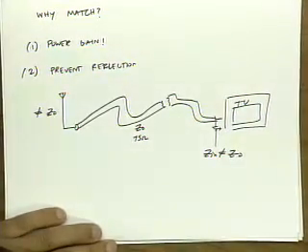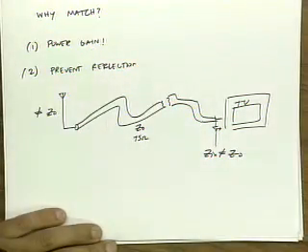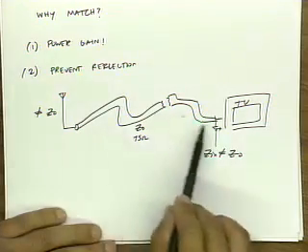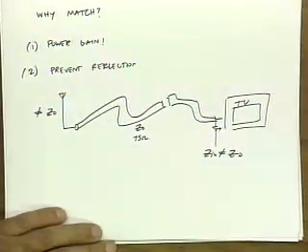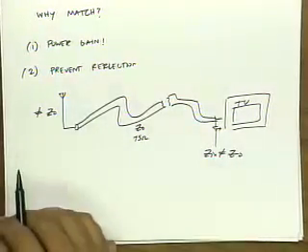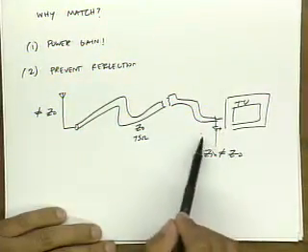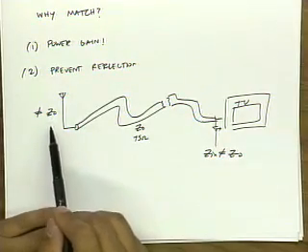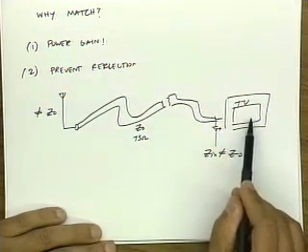What's the big deal? Well, first of all, you're not going to transfer the maximum power. That we've already talked about. But the other problem is that you're going to get reflections. The reason you don't get maximum power is that power is reflected from this television. This is something we study in 117 when we study transmission lines. This reflected power is going to come back to the antenna, and if the antenna is also mismatched, it's going to reflect again.